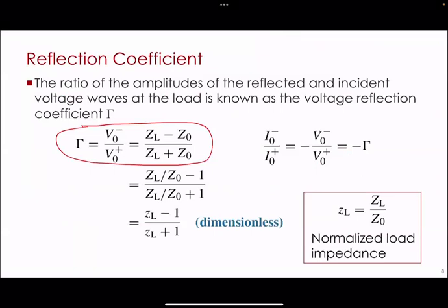This tells me the symbol, capital gamma. Now, I'm just going to say gamma, which could be a little bit confusing because I also say gamma for the propagation constant. But they're two totally different things, though they are related. Gamma is the symbol for the reflection coefficient. This here, you're rarely ever going to use to calculate something, but it always reminds you of the definition of this thing, okay? You've got two waves, some incident wave amplitude, some reflected wave amplitude, and the ratio of the reflected wave amplitude to the incident wave amplitude.